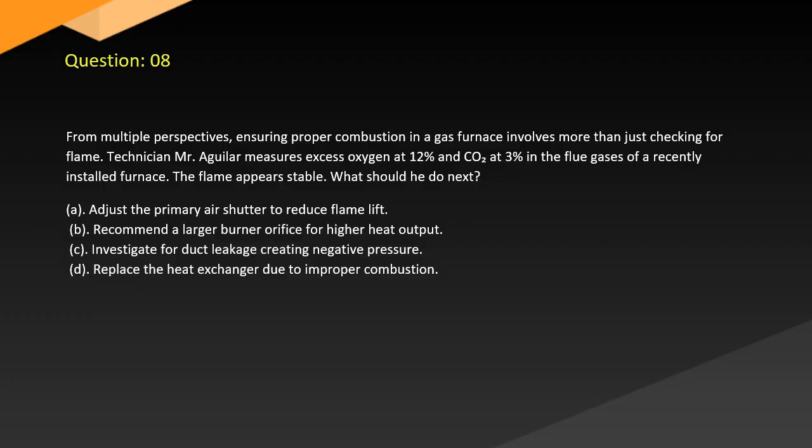Question 8. From multiple perspectives, ensuring proper combustion in a gas furnace involves more than just checking for flame. Technician Mr. Aguilar measures excess oxygen at 12% and CO at 3% in the flue gases of a recently installed furnace. The flame appears stable. What should he do next?